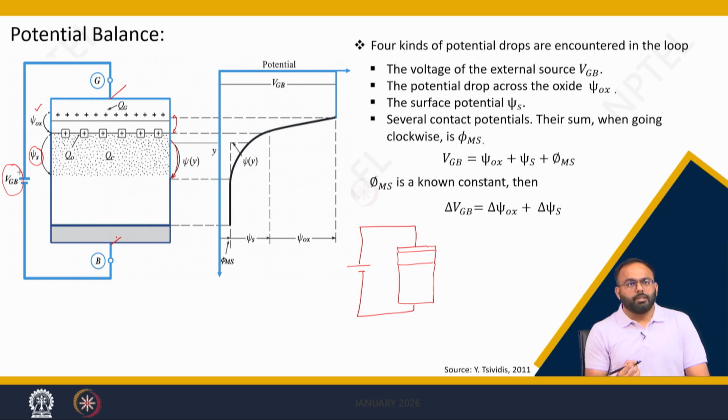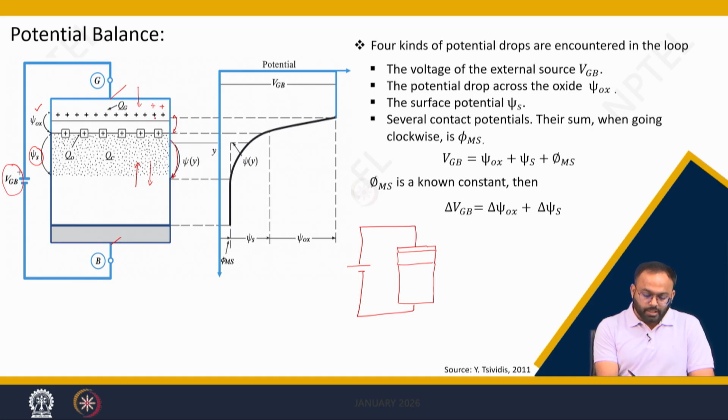So, what will actually happen when you apply a positive voltage to a layered structure of metal oxide semiconductor? When you apply a positive voltage, then there is a positive charge coming into the gate. So, the same amount of charge should leave the other plate of the structure, or you can say the negative charge of that amount will come into the other plate, right. So, if you apply a positive charge, these electric lines will first repel the holes, which is considered as a p-type body, back into the body, and hence it will leave immobile ions, right,